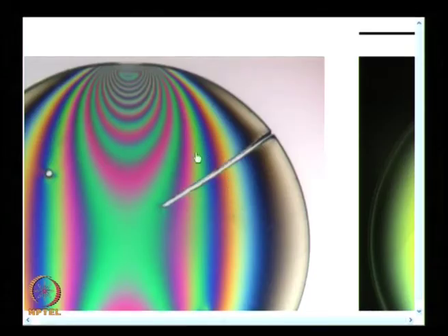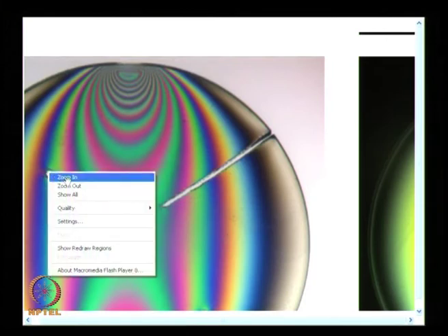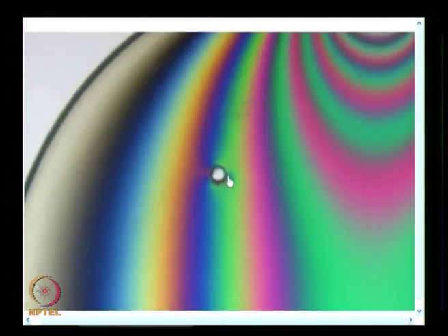And if you take that kind of care, what this fringe pattern shows is, when I have a slit made, the fringes are not disturbed, and you have a slight difference here. This is a hole that is made, you find small disturbance, though the hole is made reasonably well. It is not as good as what you had with a slot. So, the person who has made the hole needs to improve his process, because you have some small disturbance. So, even this could be eliminated by careful machining.